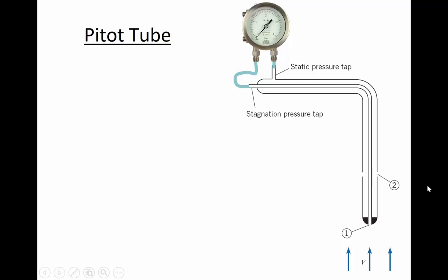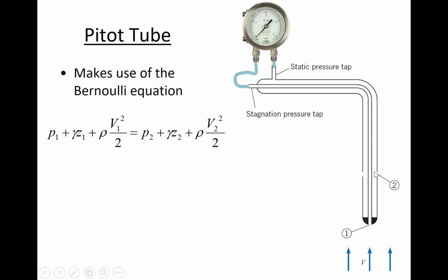And so that same idea that we had before in the stagnation tap, that there's some little extra amount that's causing the pressure to increase because the energy is transforming from its velocity head to additional pressure head, that's happening at 1. But at 2, there isn't the velocity head exchanging into pressure head. So let's apply Bernoulli's equation and look at what that says about this Pitot tube.